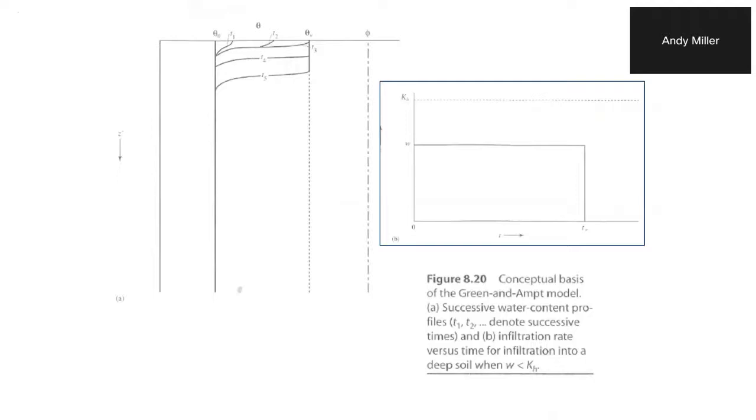This again is showing you an example of unsaturated downward flux, a wetting front, because this is porosity. So if we're saturated, the value would be all the way over to here. But in fact, physically, you have a downward motion of the wetting front, but the soil is not completely saturated. How's that physically possible? Is there anything not logically possible about that scenario, other than the fact that I only explained it in the context of it being completely saturated?